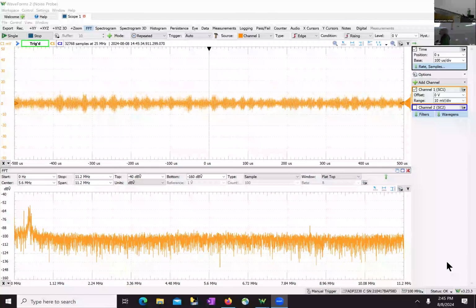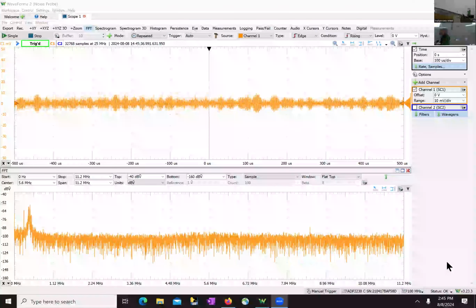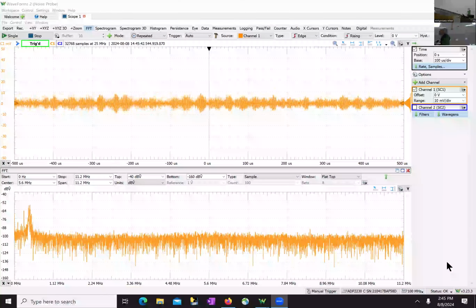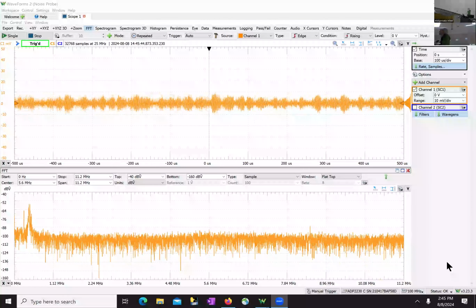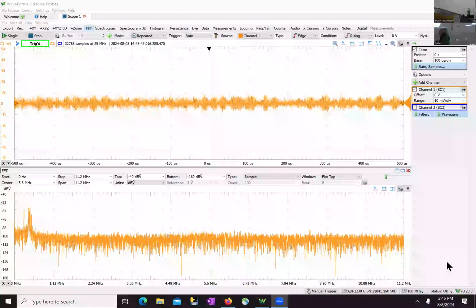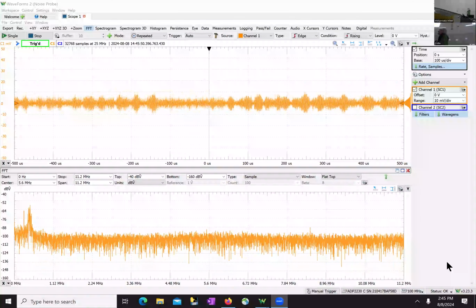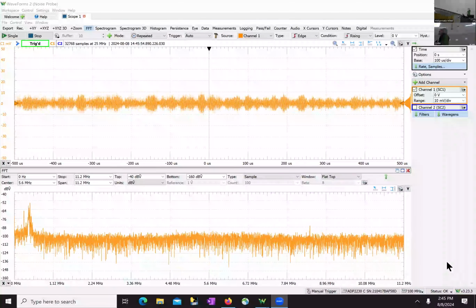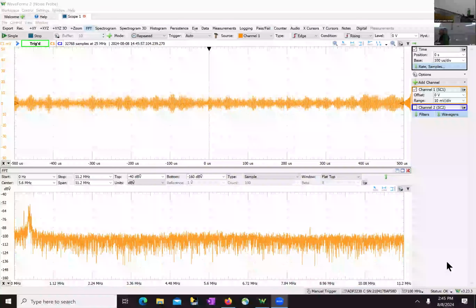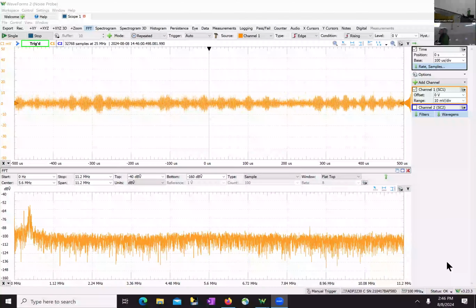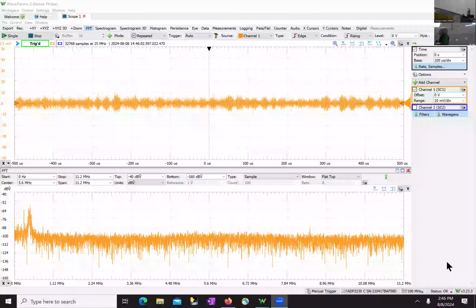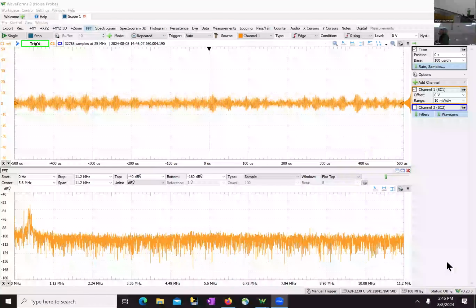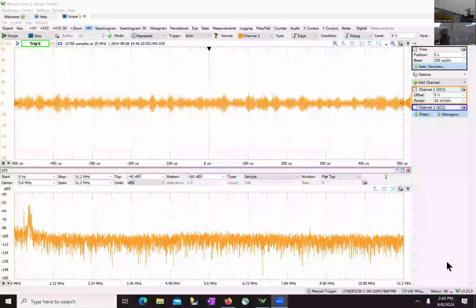The main magnetic and electric source, they also exist within that silver chloride electrode, but those are more coherent noise. So the wires that go to your electrodes act as small antennas, and those antennas pick up the noise, the electromagnetic field, either capacitively or inductively, that they're being bathed in. So the electromagnetic field interacts there.